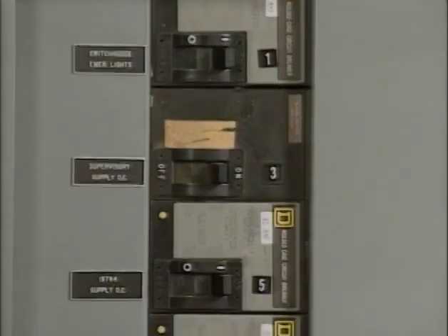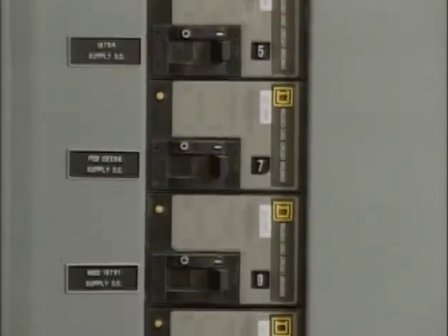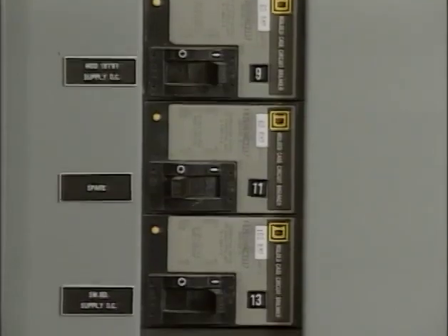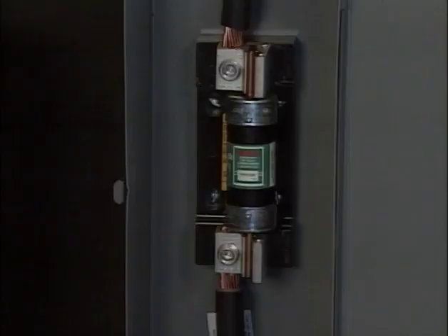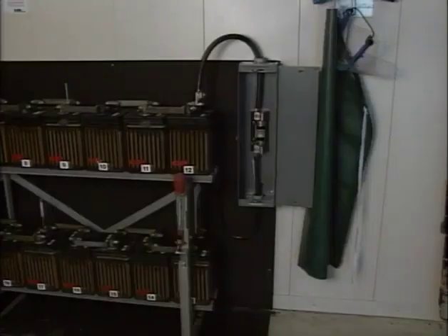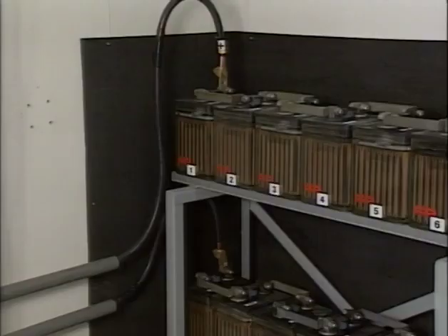In the DC supply panel, a series of breakers controls the supply of direct current to the DC loads on the system. The battery may be connected to the DC supply panel, or it may be connected directly to the charger. Also, depending on the system design, a fuse, current limiters, or a breaker may be used to protect the battery from short-circuit currents. Here, a single fuse is installed in series at midpoint in the battery. Other systems may have slow-blow fuses or current limiters in both the positive and negative cables close to where the cables connect to the battery.